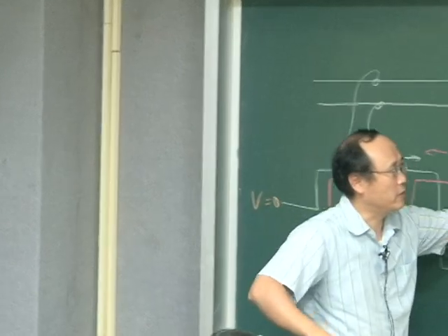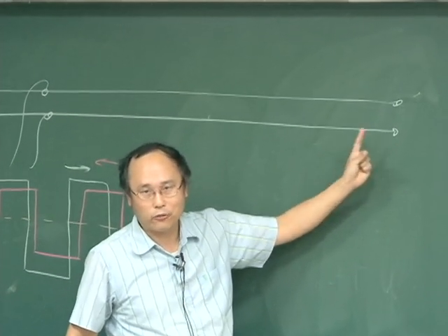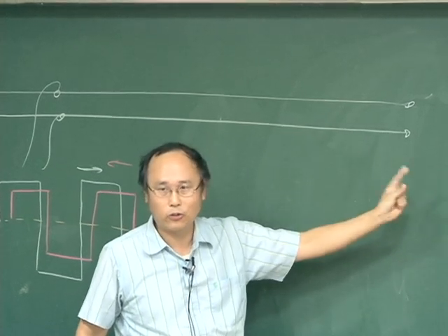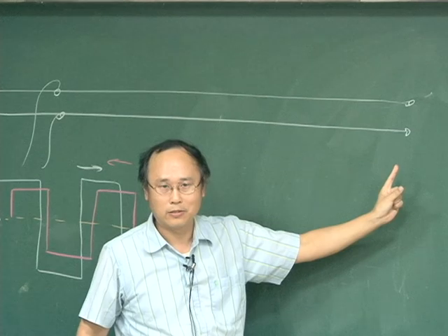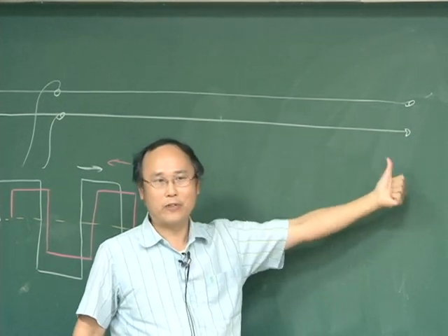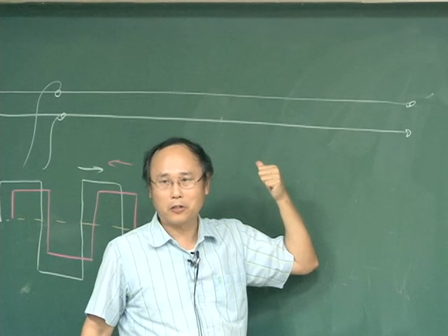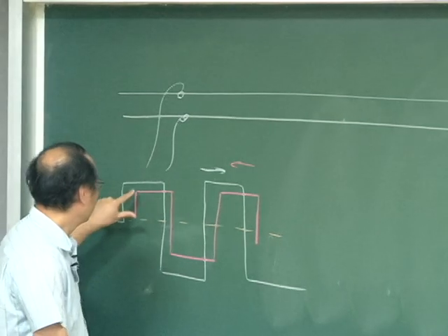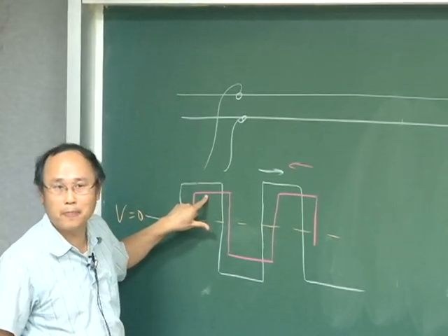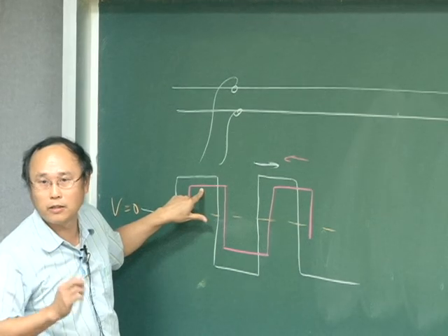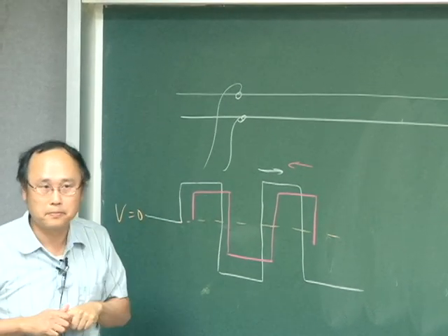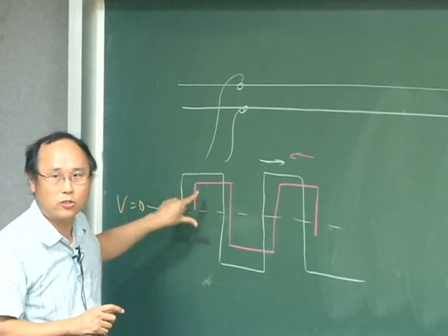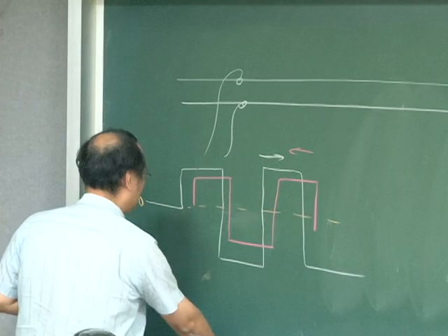Okay, this is an open circuit. Remember I told you that the reflected signal is in phase with the incident signal for an open circuit voltage. Right? For voltage, with an open circuit, the phase of the reflected signal is the same as the phase of the signal sent out, so you can see this is positive, and I still draw it positive here. Okay, understand? The reflected signal is still positive. So you overlap these two signals together and sum them together.